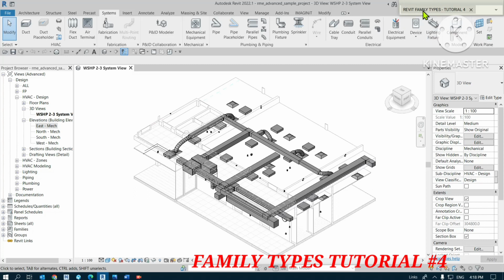You use a large number of predefined families in your project. You can define or modify these predefined families to be better suited to your project requirements. And you can also create new families for your projects by using specific templates, such as mechanical equipment, plumbing fixtures, or electrical equipment, which is this one.